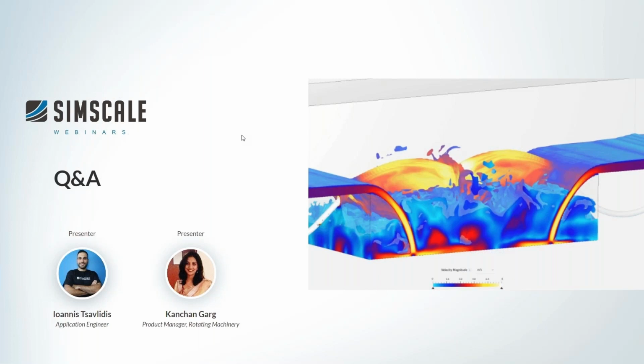If something is totally wrong and the simulation cannot start because it's going to crash right at the first time step, then we give you an error message, meaning that something crucial is missing that might cause your simulation to diverge or not work at all. Or, for example, you missed some material property, or you have empty boundary conditions, or you didn't create a mesh or something. So we will never let you run a simulation with an error.